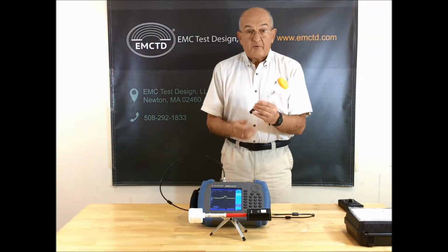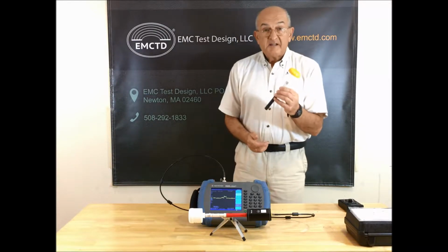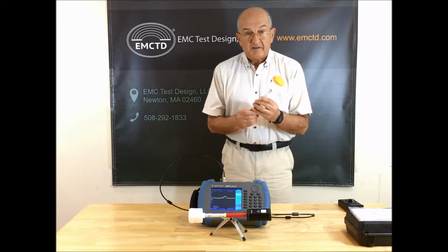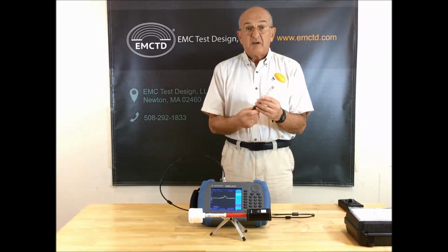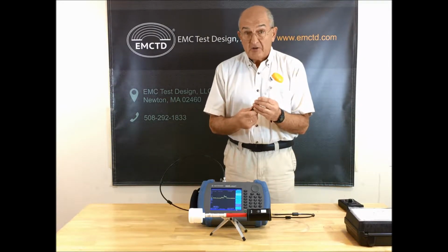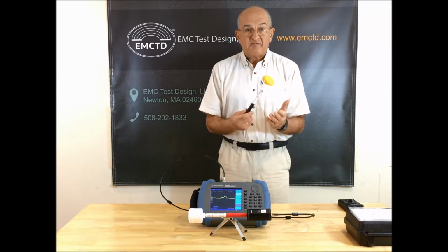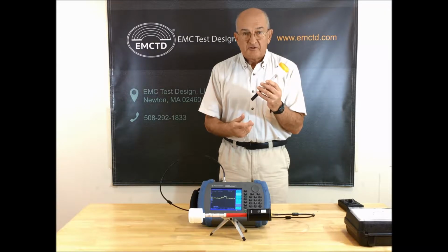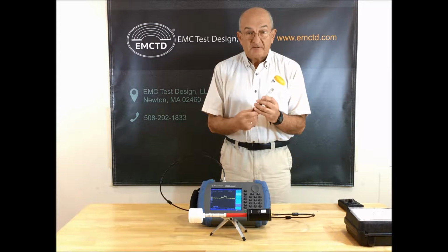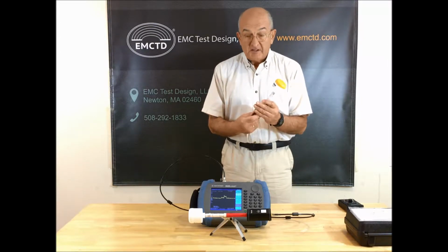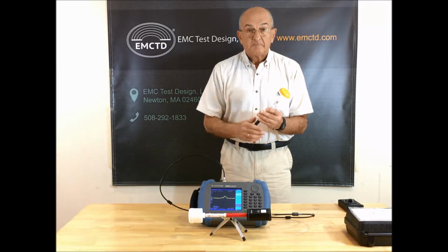There is another type of probes that we also make. This is frequency shaped probe. It has frequency response precisely targeted to FCC or ICNIRP curve. In this case, precise knowledge of the frequency is not required. So, if you are interested in RF safety aspects of measurements, this probe may be a very good solution. But for all other cases when you need to know the frequency and field strength of your signal of interest, usage of isotropic antenna is absolute must.